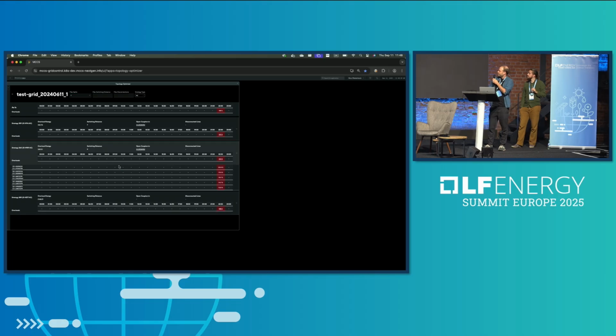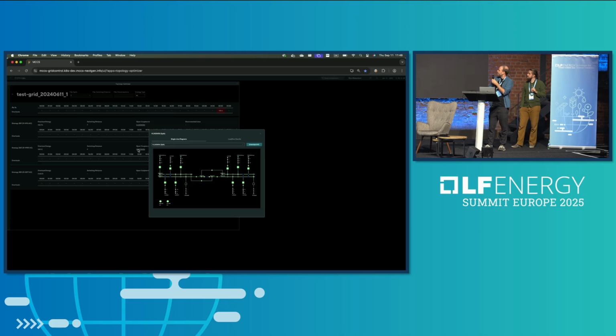And then you can also see some more infos on which critical branches and which critical outages led to this result. And you can see the substation setup. So here you can see how it was before and what you changed. And of course, you opened the busbar coupler as well. So now, or before, all the lines were connected, and afterwards, only the lines up here were connected to the lines down here, and vice versa.